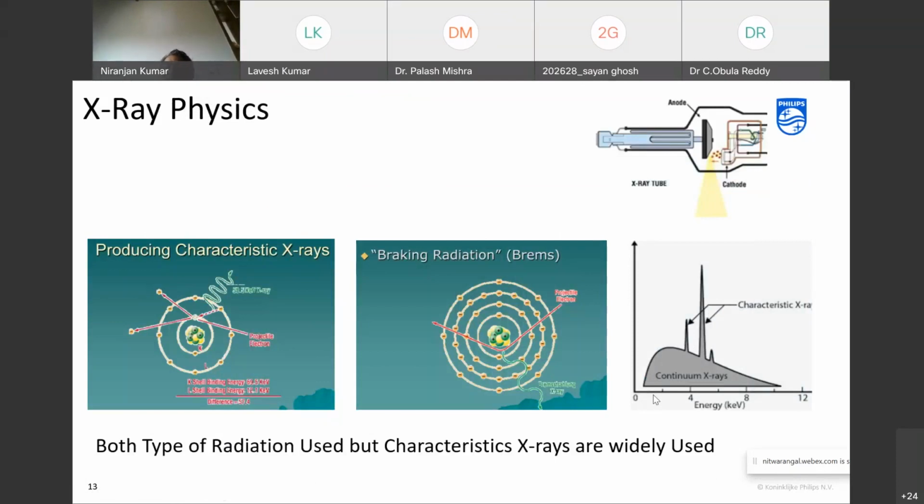Then it will start producing some X-ray of this type, which will get mixed in and may impact our image quality. Actually, I am interested only in the X-ray shown at the peak. So in grid control, we block the filament electron movement till the optimum voltage has come. We wait for the voltage, so it is some kind of control.